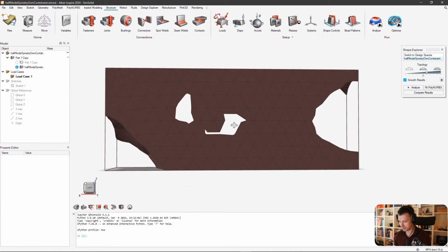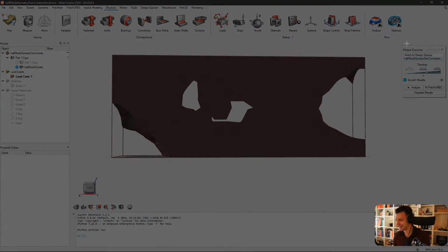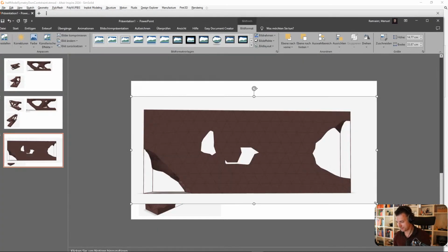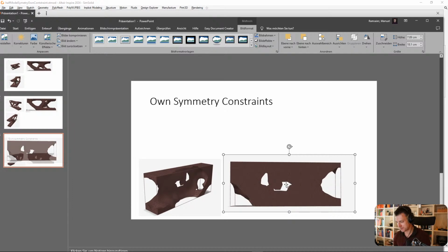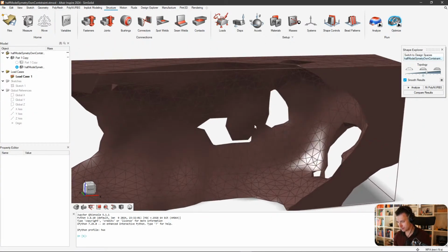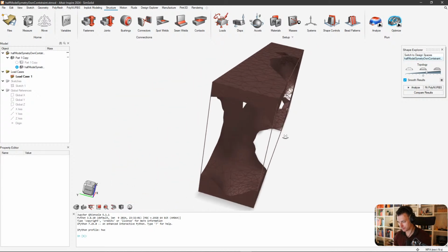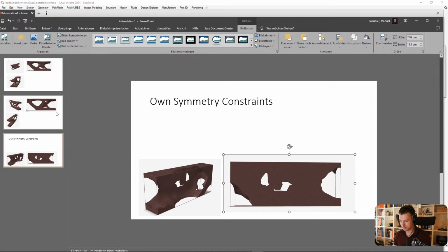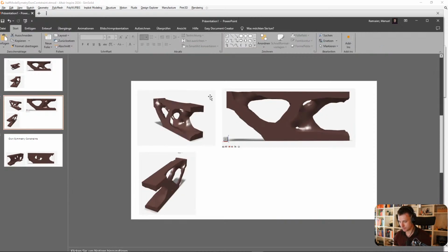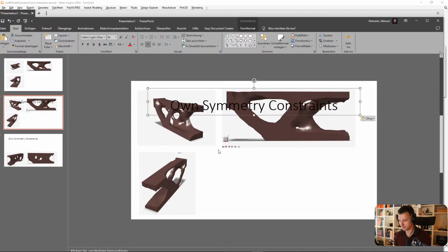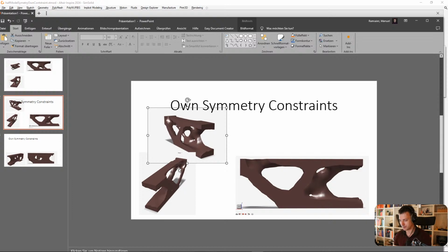Just makes a giant wall here. Yeah. Okay. I mean, if you think about momentum, inertia, and stuff like that, that makes a lot of sense to put it at the outside. And also for the bending case to put it at the bottom and the top. That makes a lot of sense. But to be honest, not so sure about the efficiency. We can maybe look also at the compliance values we got, because that's the measurement of how efficient the optimization was, right?